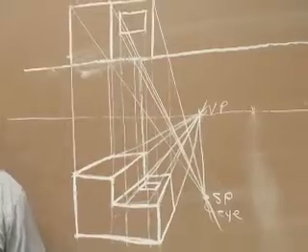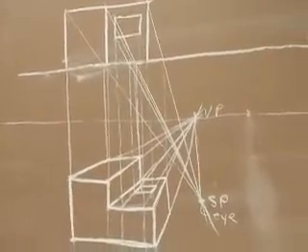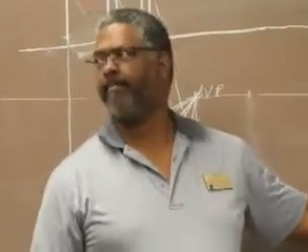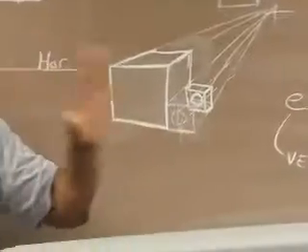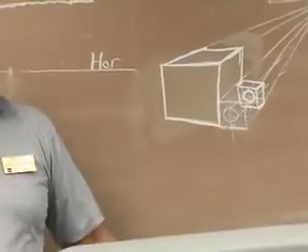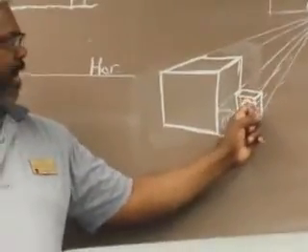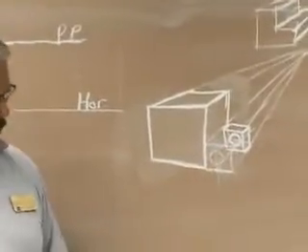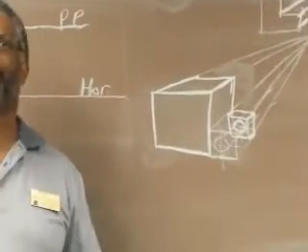In perspective, there'd be no hidden lines. Visible lines and center lines, and that's it. Don't need center lines. I need a center line initially here so I can track back to locate. Back here I'll need a light one, but make it light, because you shouldn't have center lines on pictorial drawings typically. So since you're starting with an orthographic view, you can make all of this like a light center line only so that you can locate your points on your quadrant, and then take a circle template of that size and create your circle.